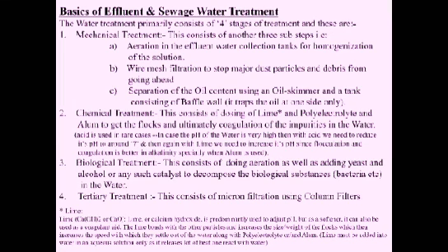You can say it's better in alkalinity, or you can also say that it absorbs a certain amount of alkalinity of the water. So if the effluent is safely around 8.5 to 9, it will come down to around 7.5 once the coagulation takes place automatically. You need to make the effluent slightly alkaline to get better results.